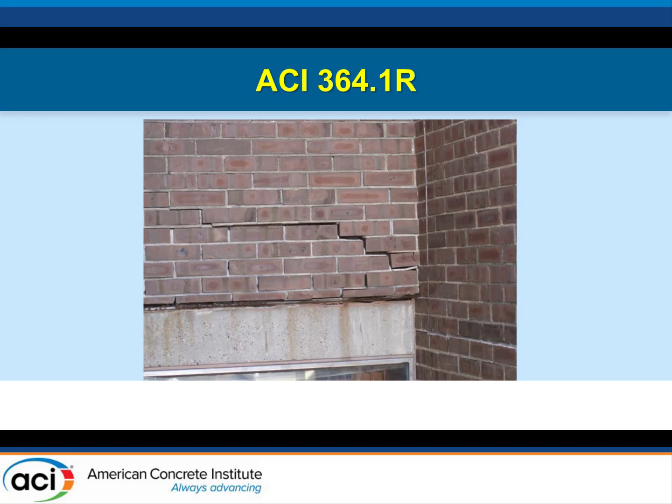And again, some of the other things you see on the upper floors, this was over another one of those window portions. When you look at cracking like this, people that do evaluations will do crack mapping of buildings. This type of step cracking is commonly found when something is deflecting. It's easy to look at this and say, well, that concrete beam that's holding that up is deflecting. And that's consistent with that crack pattern.